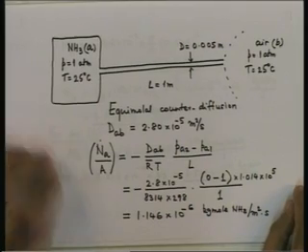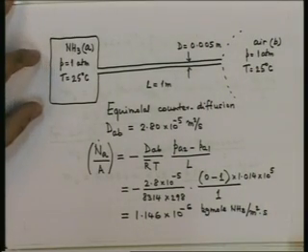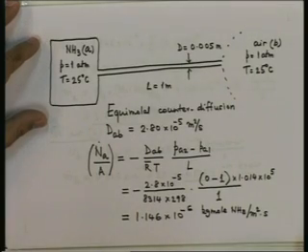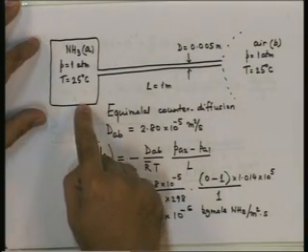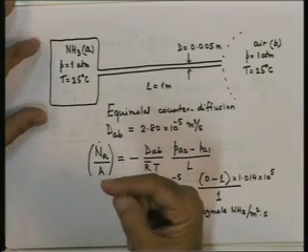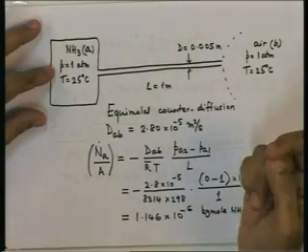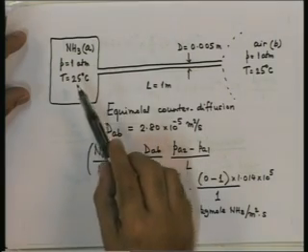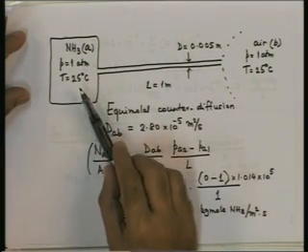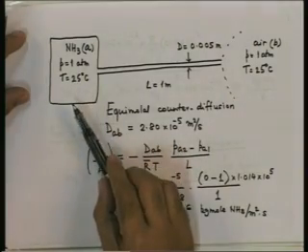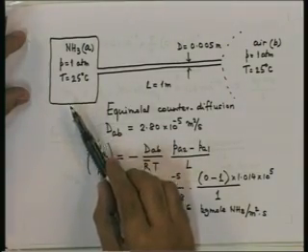And that means even if our tank contains ammonia of the order of a few kilograms, after 1 hour the amount of air that has leaked into the tank is only going to be of the order of a few milligrams of air. Similarly, the amount of ammonia which has leaked out will also be of the order of a few milligrams of ammonia, and that takes care of our earlier assumption that during this process we have assumed a steady state, and we have assumed that the pressure in the ammonia tank, temperature in the ammonia tank and the concentration of ammonia in the ammonia tank does not change.